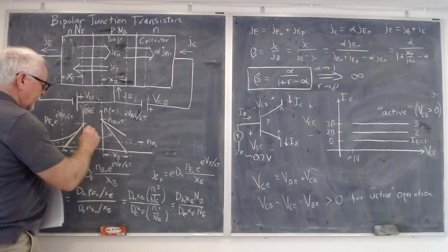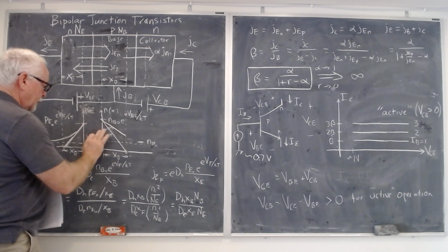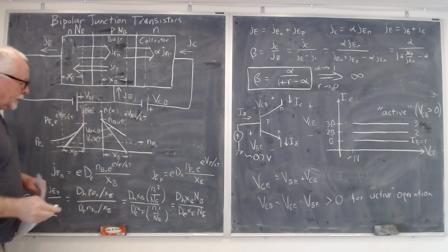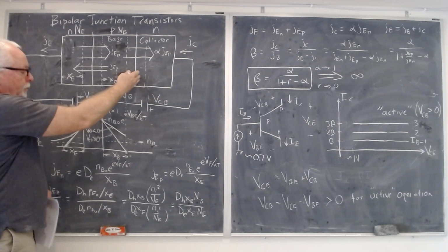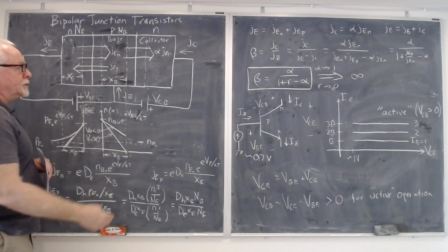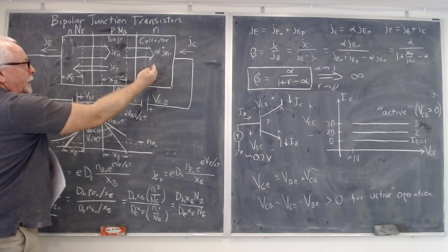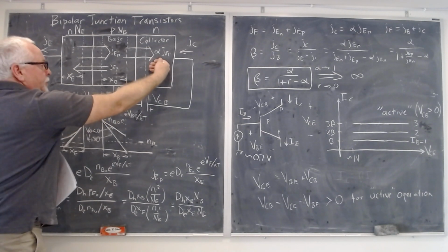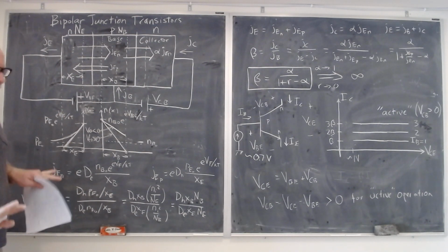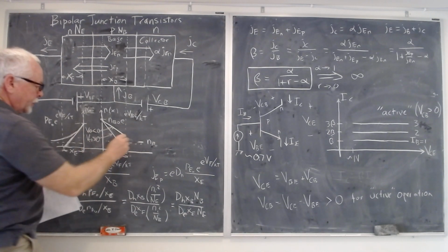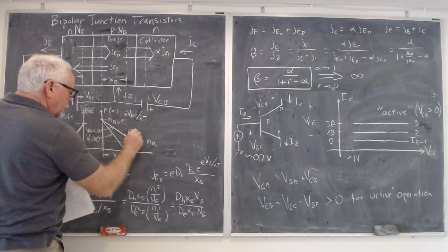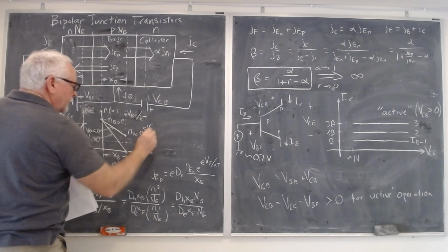And then what happens is that this curve is for VCB less than 0. Because when it's less than 0, then it's a forward bias junction, and now basically we have sort of counter operating junctions, forward biased. Now the forward biased base collector junction is trying to emit electrons that way. And I don't want to complicate this diagram because there's no reason to. All we got to do is realize that now this point is N0 times e to the qV